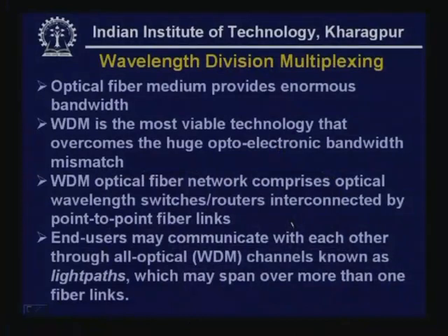And wavelength division multiplexing is commonly used in case of optical fiber, and particularly we have observed that optical fiber medium provides enormous bandwidth, and since it provides enormous bandwidth, WDM is the most viable technology that overcomes the huge optoelectronic bandwidth mismatch.